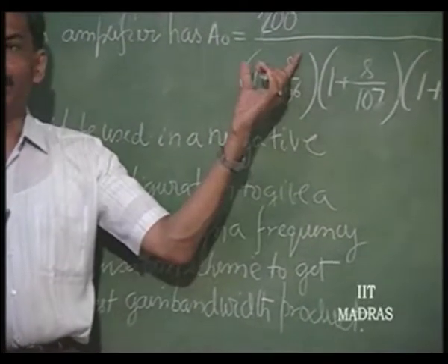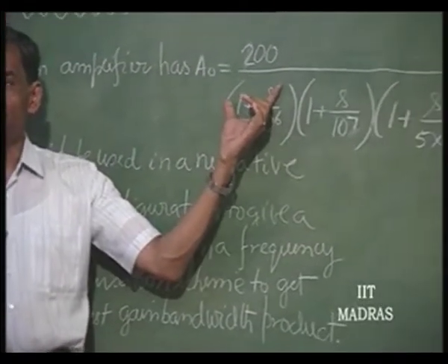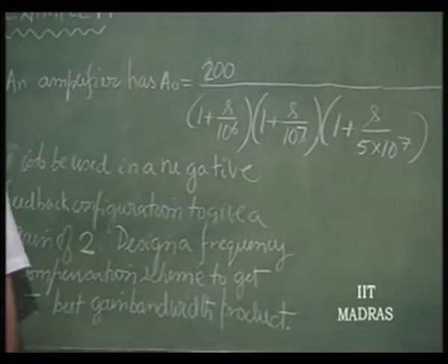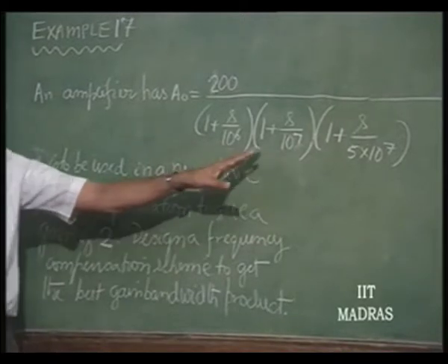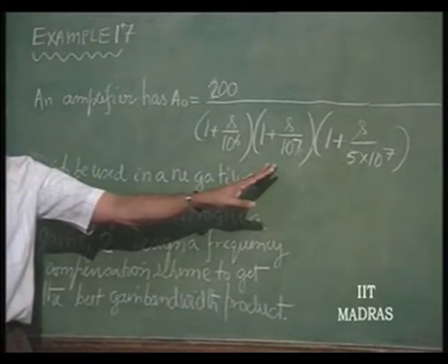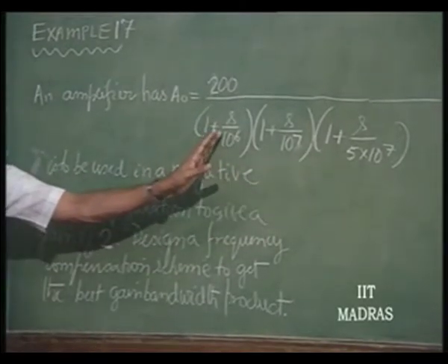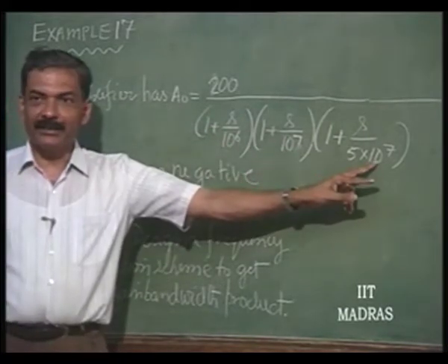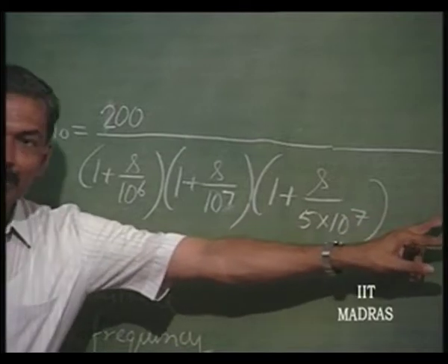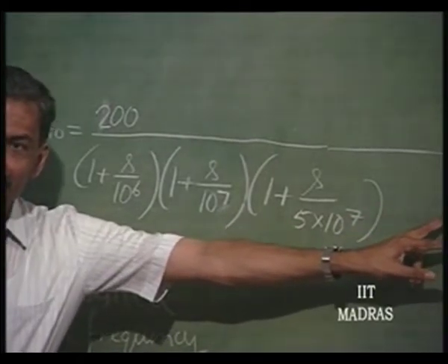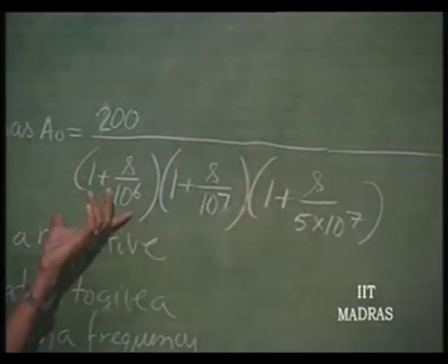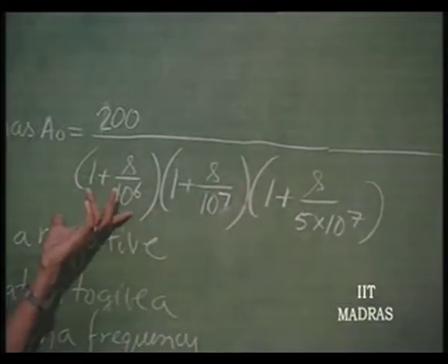You would like to retain this as a dominant pole, which means now we have to cancel the next pole, which is influencing this in terms of phase shift, so that this becomes dominant. That means, if this is cancelled, the distance between this and this increases enormously, and another pole is going to be introduced far away, so that these 2 poles do not come into picture, and this is the dominant pole. That is the idea behind widebanding.